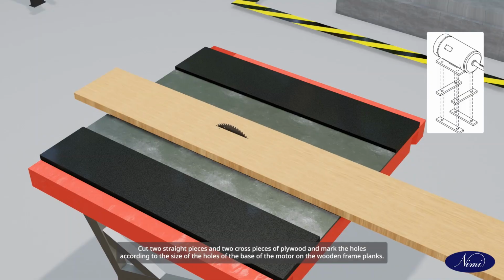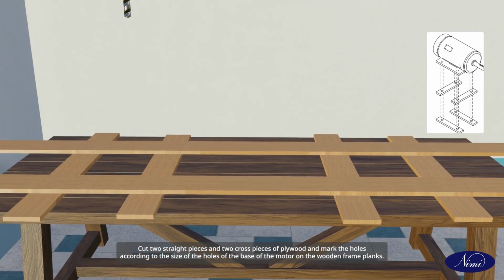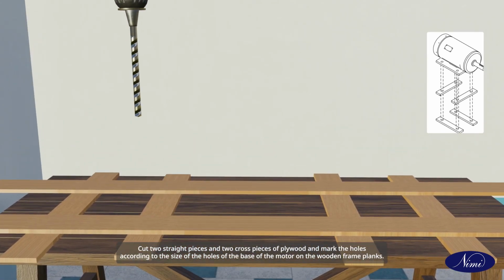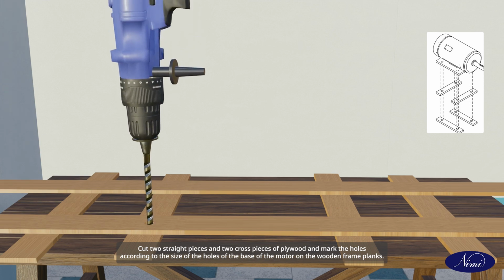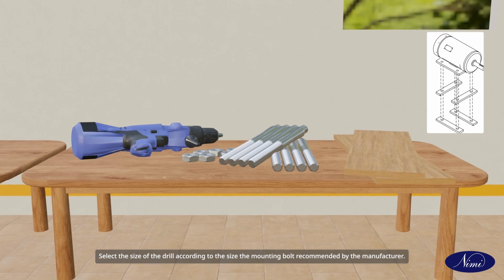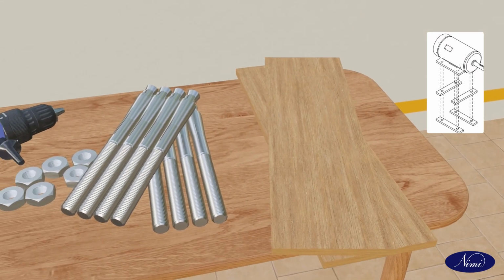Cut 2 straight pieces and 2 cross pieces of plywood and mark the holes according to the size of the holes of the base of the motor on the wooden frame planks. Select the size of the drill according to the size of the mounting bolt recommended by the manufacturer.